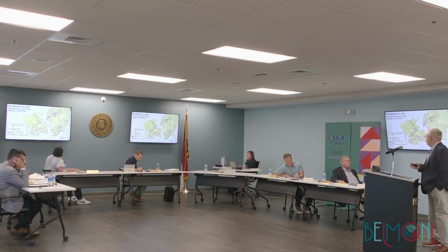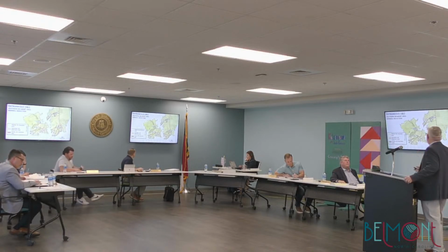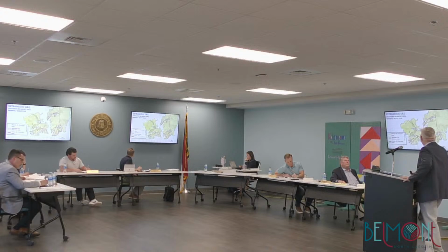This area here, I've got this as minimal I&I. These are not major contributing areas. Now, certainly, it's not a bad practice to go down there and find one or two clean outs or something that may be letting in, but it's not a major contributor. We're not seeing that the flow coming from there is mainly tributary flow.